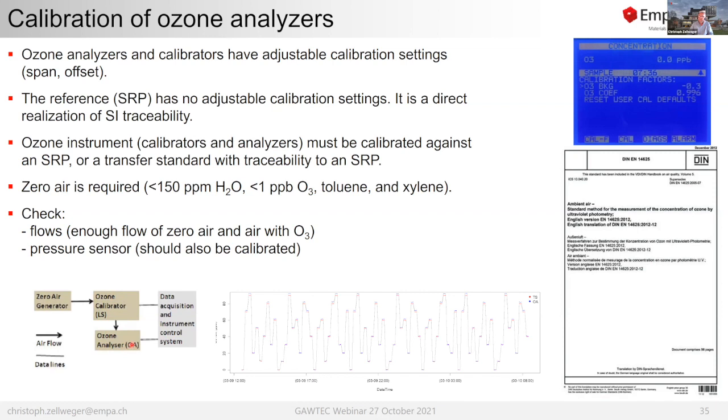And then you have in principle 2 options. You can adjust the calibration settings in a way that you have a perfect match, or almost a perfect match, as good as you can do. Or you can also apply post correction to the data because you know the relationship, you know the bias, slope and intercept, and you can correct it afterwards. So there are 2 possibilities.